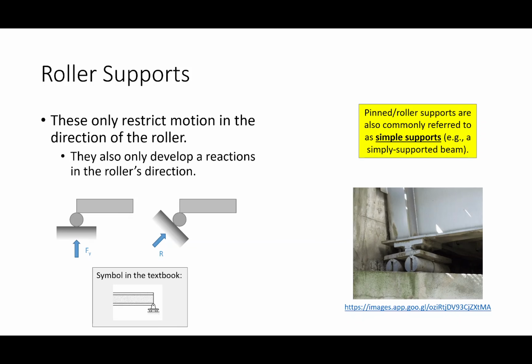It's like a vulcanized rubber pad with steel plates in it. It's sort of like a super stiff jello, and it can move a little bit. We want the bridge to be able to move a little bit so that it can thermally expand and contract and not cause damage to adjacent elements. Does that make sense? That's just one thing to think about.